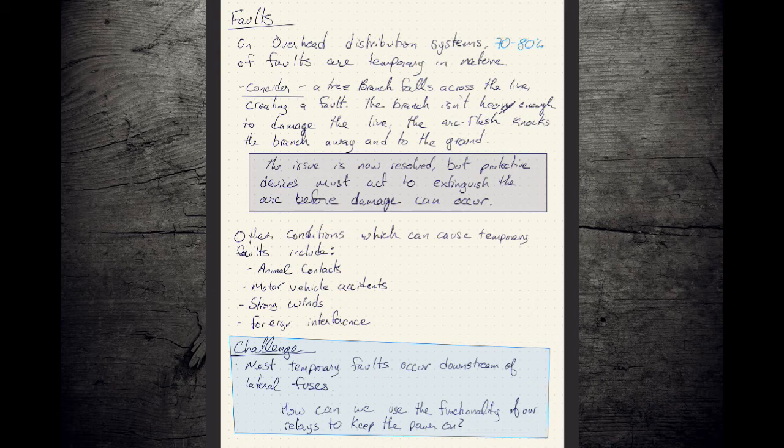So this is great, right? Now we put one of these up and we have a fault and we turn the power off, and then we can give it a couple of seconds to wait for things to settle down and we can close it again and probe that fault. We say, hey, I'm going to try a second time. Is the fault gone? Yes? Awesome. Problem resolved. Is the fault there? Oh, crap. Still faulted. Open up. Maybe we'll try a third time. Last try. Power's back on and it holds. Okay, we're done. Or power's back on and it's off. Whatever this is, it's not temporary. It's a permanent problem. Something's busted. Turn the power off, leave it off, and we're done.